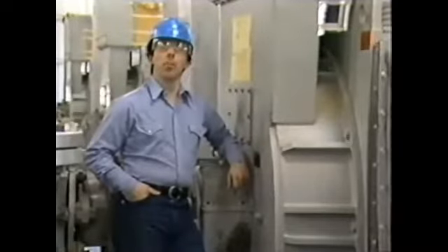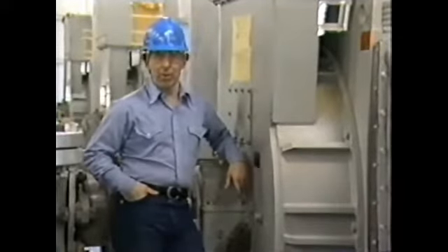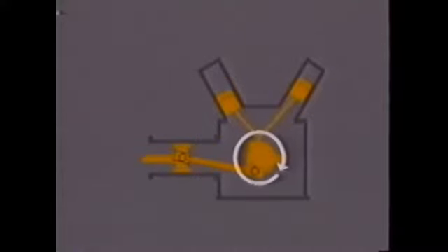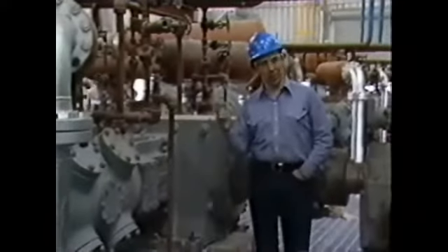The power to operate the compression unit is usually supplied by either electric motors or engines. The most typical, however, are combustion-type engines. In these, power pistons are connected by connecting rods to the crankshaft. In addition, the crosshead is connected to the crankshaft by a connecting rod. Thus, rotation caused by the power pistons is translated by the crankshaft, connecting rod, and crosshead into reciprocating motion, which powers the compression unit. Now, just as lubrication promotes smooth compression unit operation, lubrication of the drive unit is equally important. However, lubrication of the drive unit will be covered in a later module.